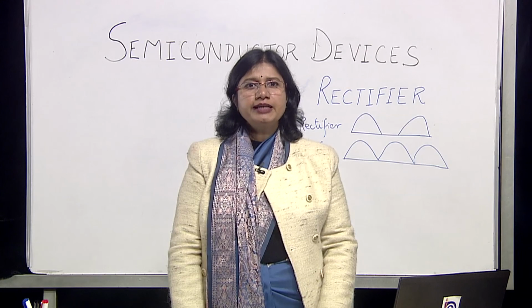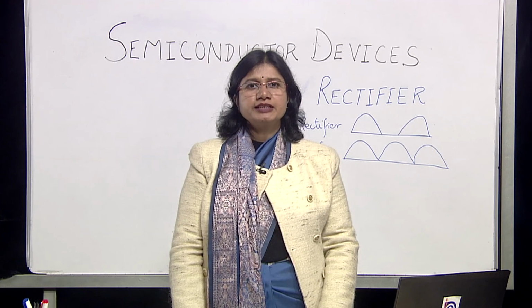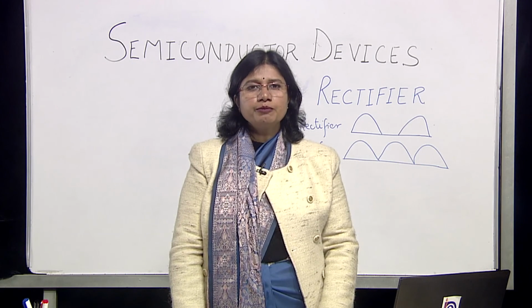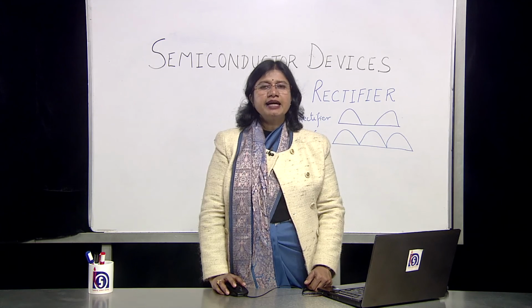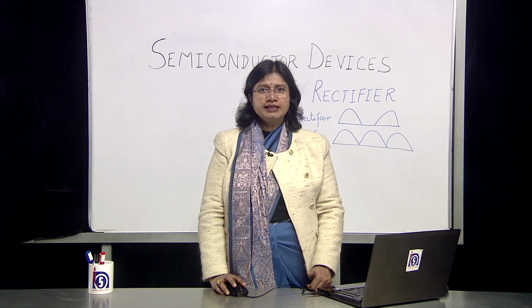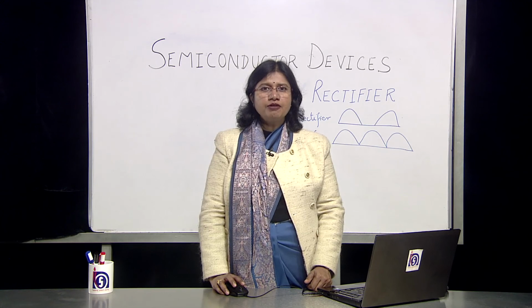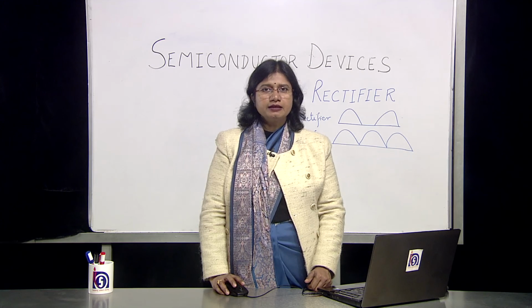Over here, with the help of an LC filtering circuit, we are going to remove the rippling effect which is otherwise seen in a full wave rectifier without a filter circuit. So, by application of a filter circuit, our signal is refined. Let's have a look at our signal.